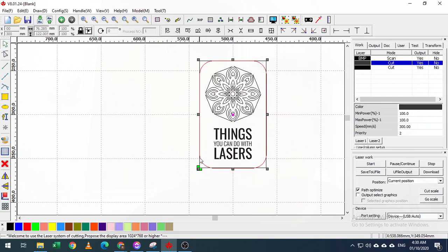So as you can see, this cut highlights the outer part, the actual profile of the entire workpiece, which we will be cutting last, because in laser cutting engraving you need to work from the inside out. If you work from the outside in, the laser might cut off your profile. So what would happen then is your workpiece might move, and it might offset the alignment of your work.